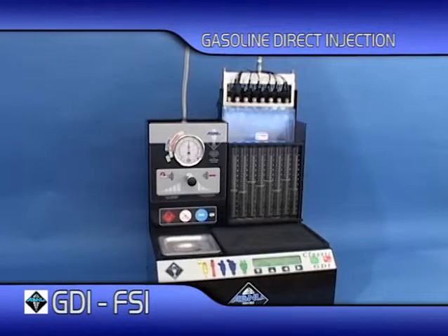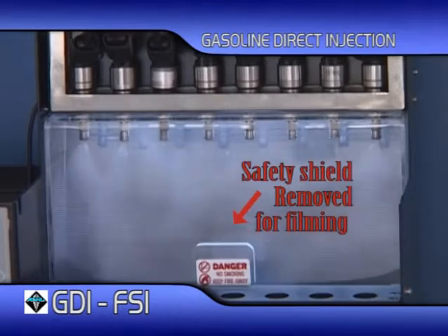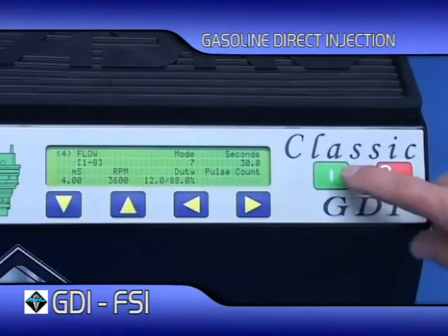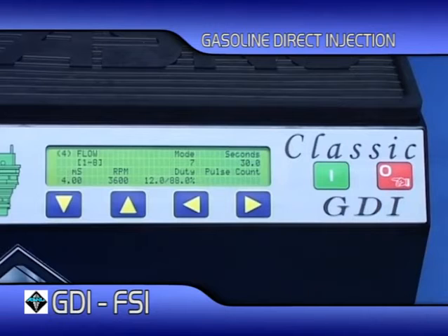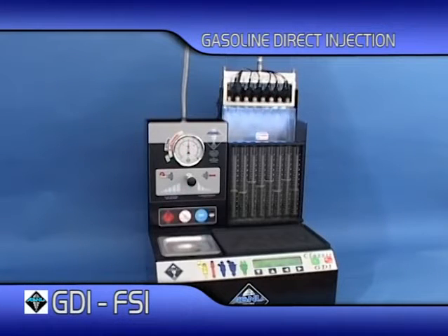These injectors are being driven with the correct peak and hold currents in sequential sequence, as they would be on the engine. Correct electronic operation of these injectors is far more important than running them at the potentially dangerous high operating pressure. To enable a safe and easy examination of the injector's performance, the ASNU system runs at a lower and safer operating pressure of approximately 5 bar.